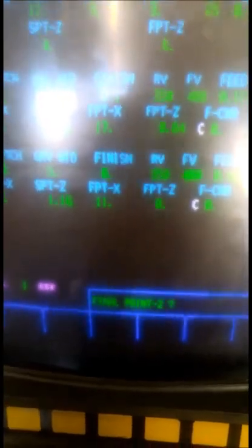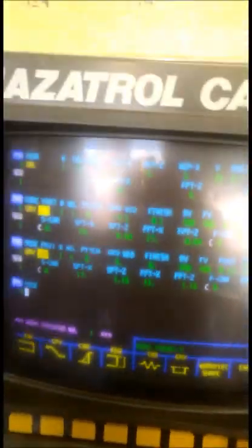Finish point in X, so I've got a hole going through at 12 mil, so I'll just set that at 11, and then it'll just part it off, not bother cutting nothing in the middle there. And then finish point in Z, like I said, it's still measuring off the same side of the tool, so 1.16. No finish corner, set surface at 8. And there we are, that's the whole program, so I can hit end on that.